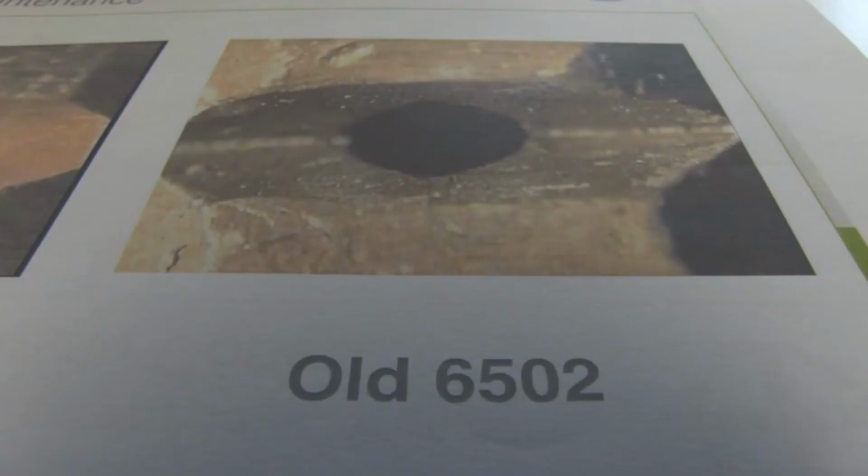So if you've got an old nozzle, the shape of the nozzle is deformed. Essentially the hole's actually bigger than what it should be, and it's not putting out the correct pattern. So you'll be using a lot more emulsion. You're wasting product. You risk staining that area or overdosing the area and spraying past the point of runoff. So it's important to check your nozzles periodically.